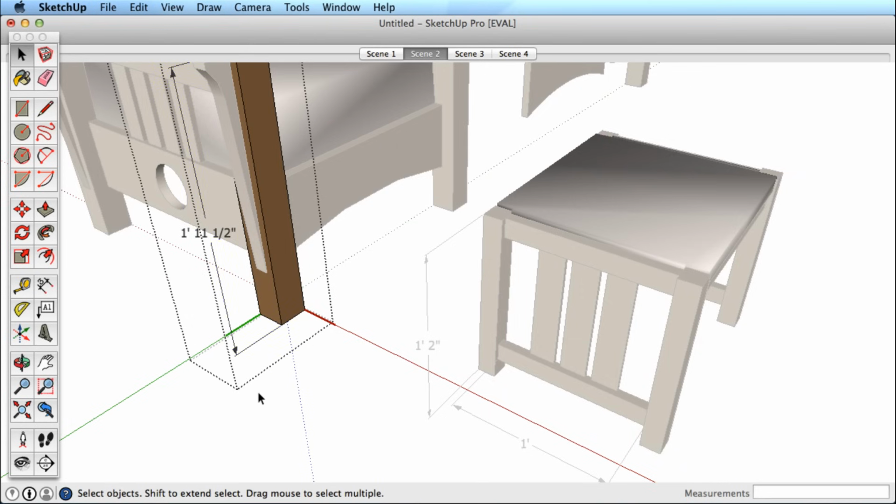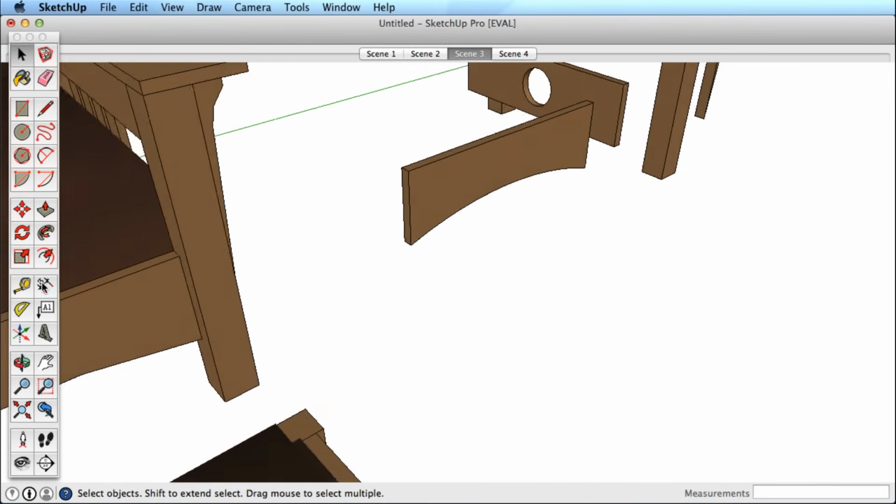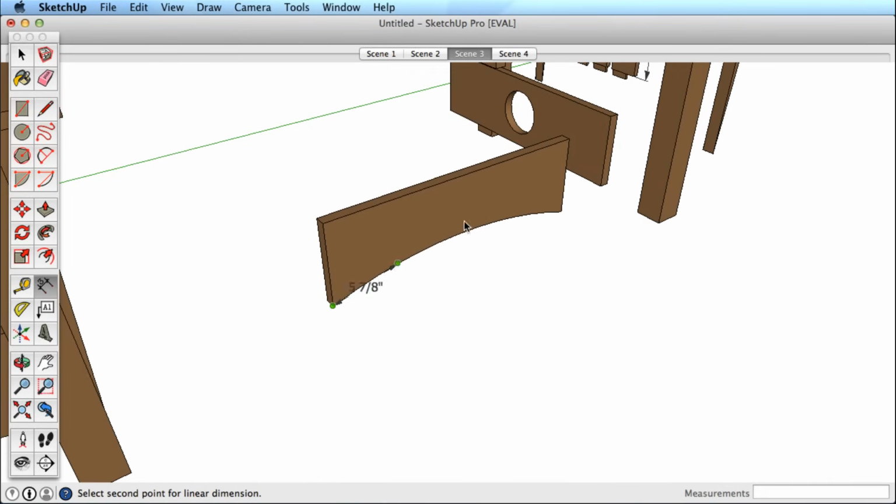As you pull off dimensions, you can choose from several directions from which to measure. For example, measuring between these 2 points gives us different results if we pull in the red, green, or blue directions. We can also pull away in a perpendicular direction. You can also dimension an arc or circle to find the radius of an arc or the diameter of a circle.